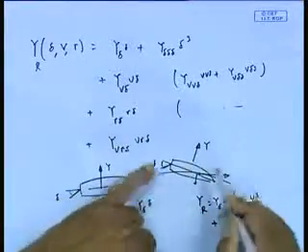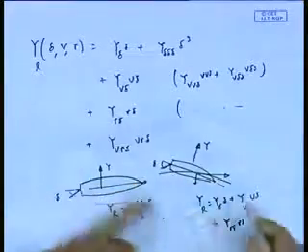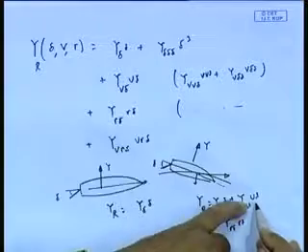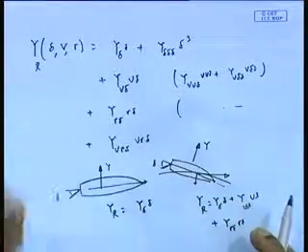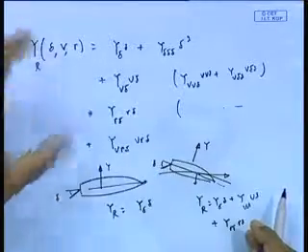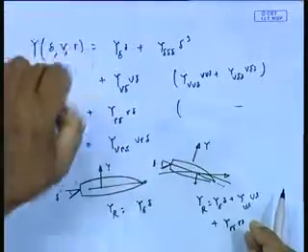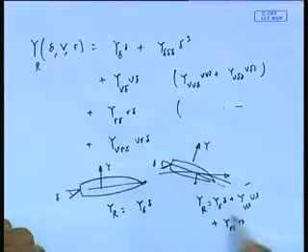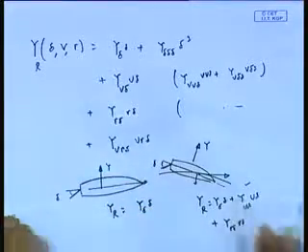There can be a correction because the y force now applies on a hull which already has some v. So y is a function of v and delta, and therefore the rate of change of y against v and delta, del square y by del v del delta into v delta, this term comes in. This is the physical meaning of that.